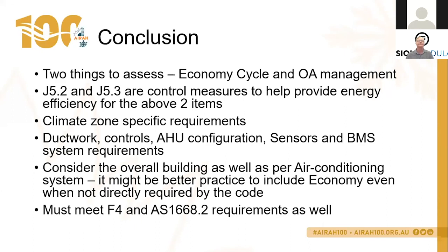So yes, sizing dampers and ductwork appropriately to achieve the airflow velocities that allow the sensors to operate correctly is also something you should take into consideration.